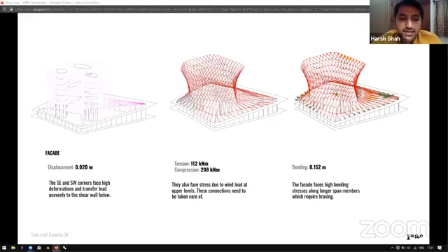And the facade study was also important to understand its stability. The deformation, axial, and bending forces were taken into account. It was noticed that it faced high deformations along longer spans and high tension and compression along major wind load directions, and bending due to inadequate support in some locations.